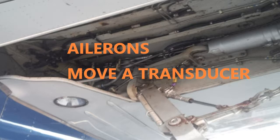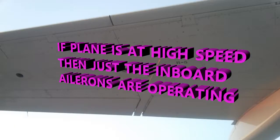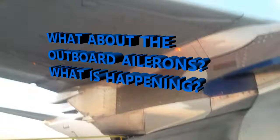And what happens with your outboard ailerons? Remember I said you have inboard and your outboard ailerons. If the plane's at a low speed, then all the ailerons are being used. If the aircraft is at a high speed, then not all of them are going to be used. It's only going to be the inboard ailerons in that particular instance. And so what's happening with the outboard ailerons at high speed?